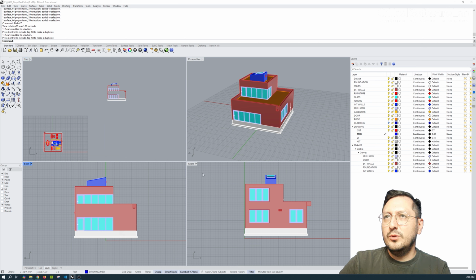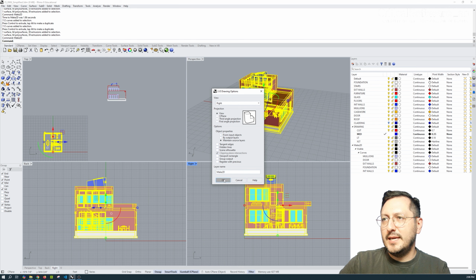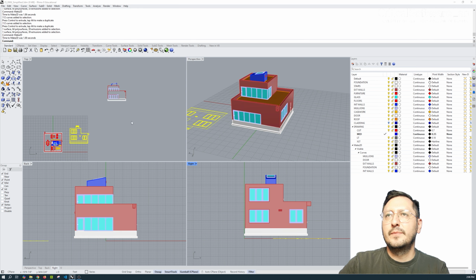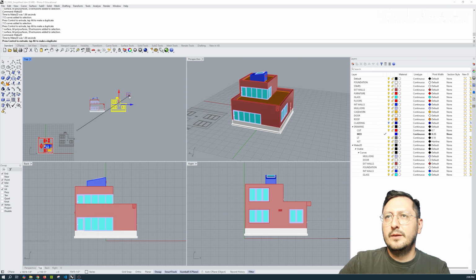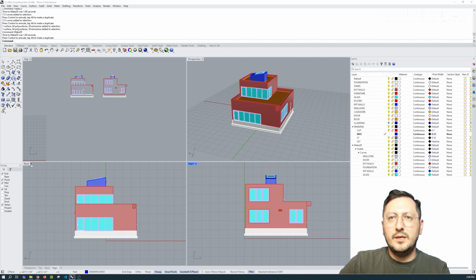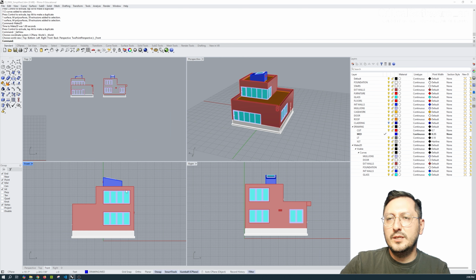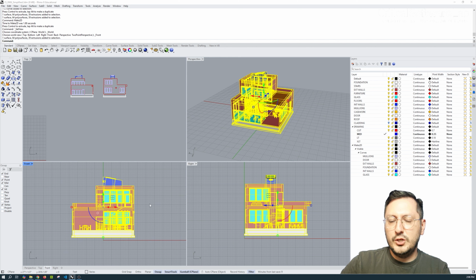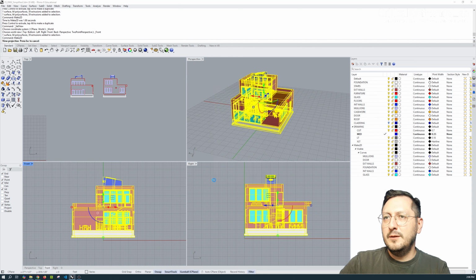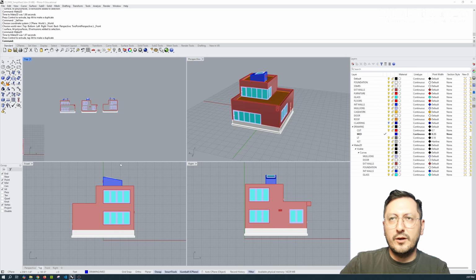And now let's do the right elevation. So we're going to do the same thing, and we run make2d again with the exact same options. And now we have our right elevation. Pretty simple. Now let's try it again from the front. So I'm going to switch the view from the back to the front so we can get our front elevation. Make2d. And I'm just kind of loosely arranging these over here. I will align them later on when it's time to finalize the drawings.